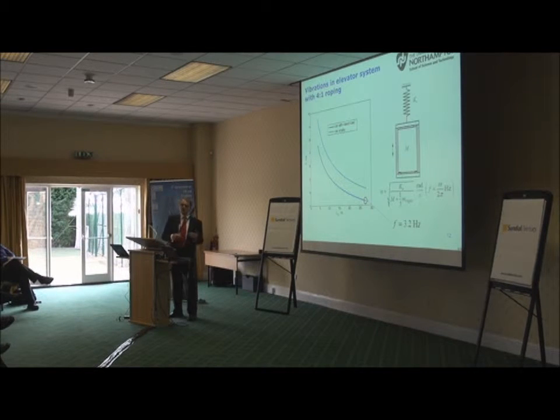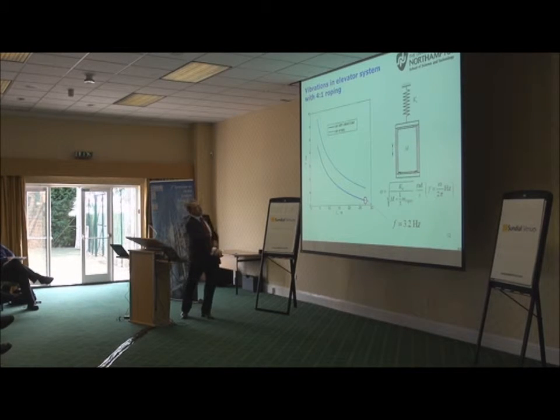If we are talking about the effective stiffness, it depends on the number of branches of rope. For the effective mass, we need to take into account, for example, the masses of the ropes, and there's a formula for that. And we calculate this over the range of travel height. The length of the ropes changes, and here I have two curves calculated from this equation.